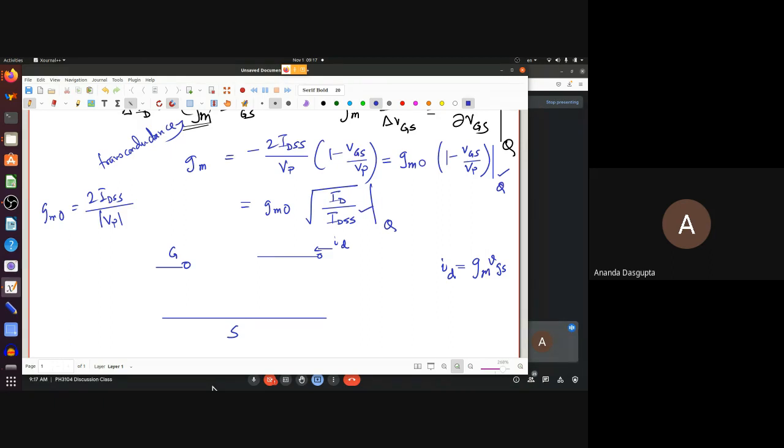If you remember your h parameters at all, you should be able to say this very easily. H parameters, z, y. We did this all the time. We essentially had a Taylor series expansion, and then we tried to make a circuit out of it. So what kind of circuit component will give you a current id, which is gm times vgs? vgs, remember, is the voltage here. A voltage controlled current source.